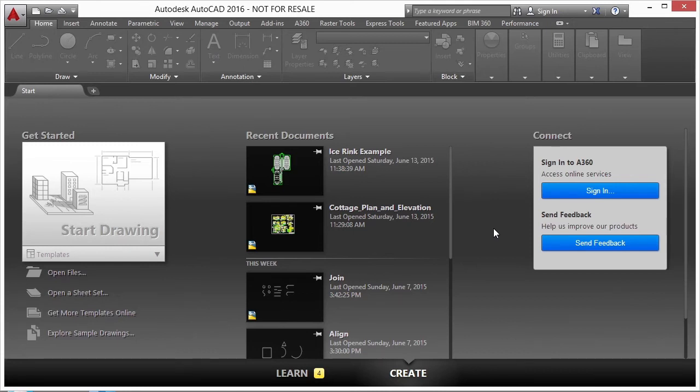When AutoCAD first started, it was just a drafting tool, but over the years now it's developed into much more than that. It's a database management tool. Now, sometimes that data in your file will change or need to be changed. I want to look at the rename command. This command will help you change the names of assigned items such as layers, blocks, dimension styles, text styles, and so on. Having a system in place that standardizes your naming procedures is good CAD practice.